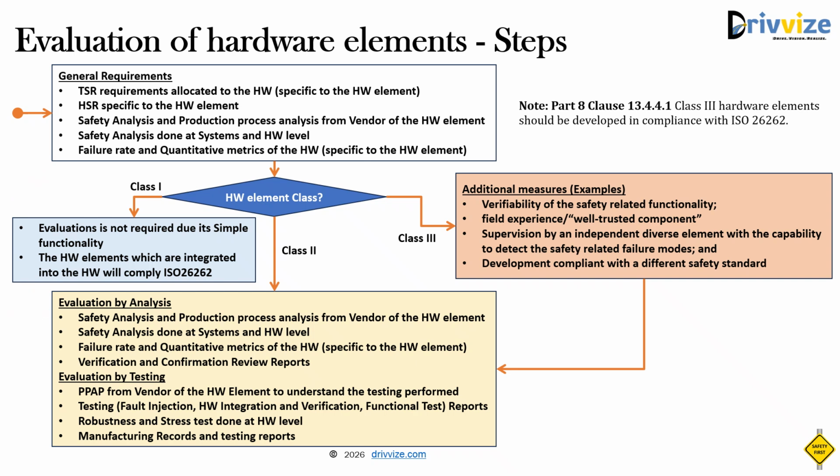The first step here is evaluation by analysis. This means we review the data provided by the vendor and combine it with our own safety analysis, hardware metrics, verification results, and confirmation review reports. Based on this, we check whether the risk of violating a safety goal is sufficiently low.